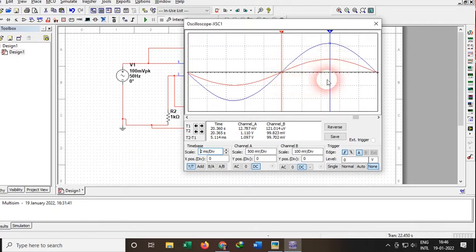Similarly, if you want to check the difference between the topmost part and the lowermost part in voltage, you can do it by subtracting the voltages. Suppose I have taken my cursor from here to here. To find the voltage difference between these points, we subtract the voltage at the peak-most point from the voltage at the other point. We can see here the voltage at T2 is 1.11 volt and the voltage at T1 is 469.084 millivolt. So the difference is 640.958 millivolt.